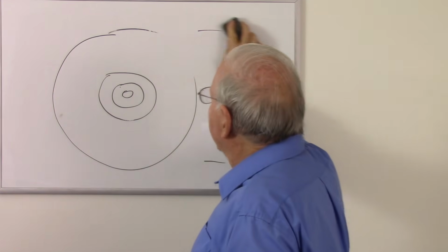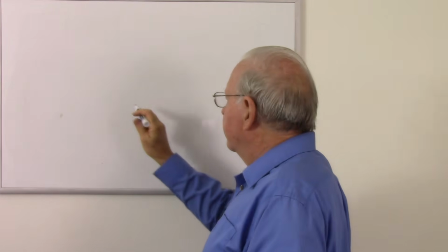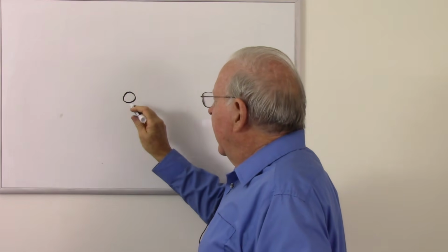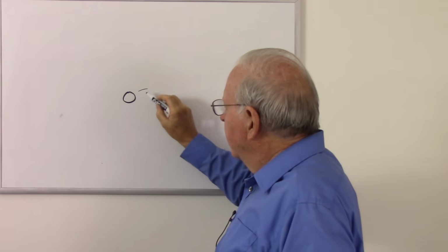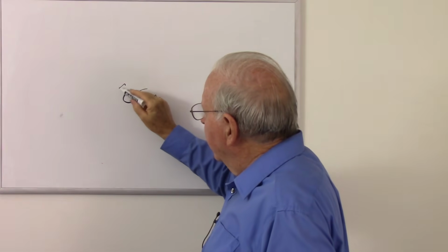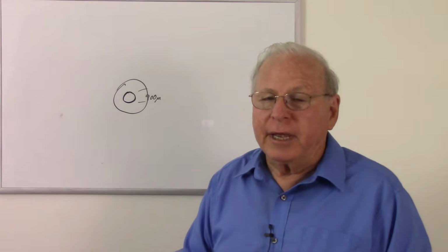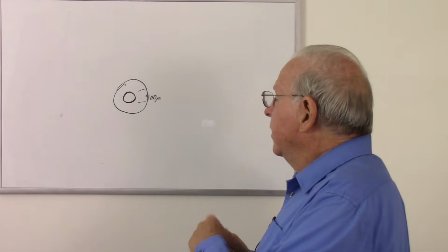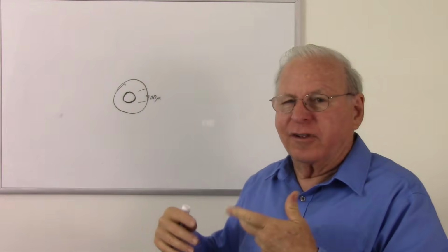Okay, so now we've got that established. We've got our tight buffered fiber, so I'm just going to make that this big. And so that's going to be core, cladding, and your two buffers, about 900 microns in diameter. And then around that we're going to have what's called the strength member, which is going to be Kevlar fibers, or aramid. Kevlar is a trade name of DuPont. Aramid is the generic name. There's going to be this bright yellow cord that's inside.